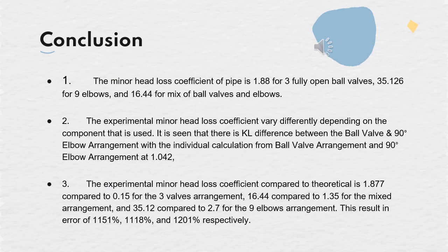The conclusion for this experiment is as follows. First, the minor head loss coefficient for the pipe is 1.88 for 3 fully open ball valves, 35.126 for 9 elbows, and 16.44 for a mix of ball valves and elbows.